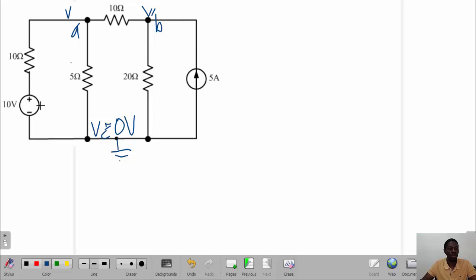And so what we're going to do in this case, if you remember, there are two scenarios that you can use. One is to convert this into a current source parallel to a resistor, or you can create an imaginary node here. You create the first case scenario, and by creating the first case scenario here, this node, which we can label as D, the voltage across this node VD is simply going to be equal to 10 volts.